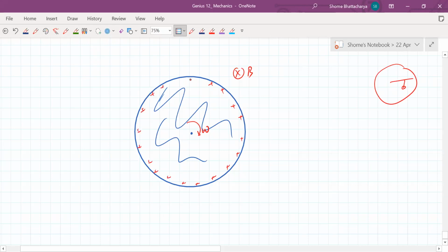Okay. So there is a charge gradient, like a potential gradient, because of redistribution of charge. There's a lot of charge here, then a little less charge here, then a little less here, then eventually there's some negative charge, a very high density of negative charge near the center. So there are radial electric field lines which are formed. The internal electric field is forming radial lines like this.